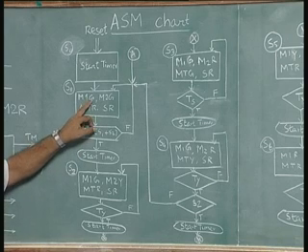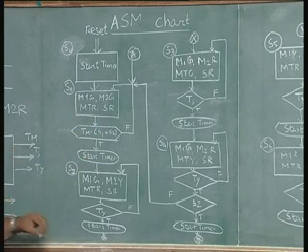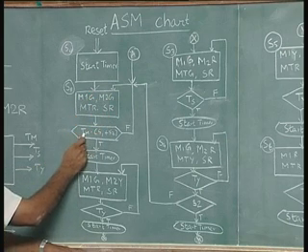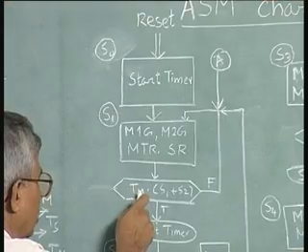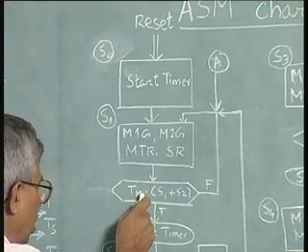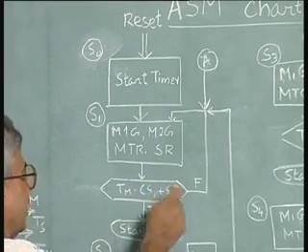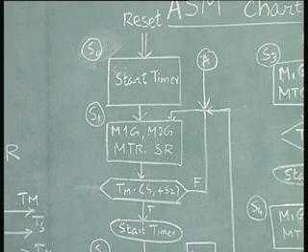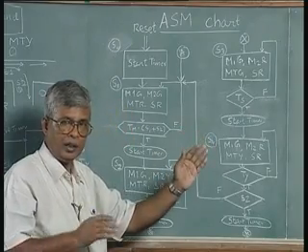So, it will be first green. Each of these states corresponds to one of those diagrams we discussed earlier. The only thing is, the machine will stay in this state until the main road duration is over. As long as the main duration is not over, or if one of the sensor signals S1 and S2 is not on, in either of these two cases you continue to be in the main road flow, green from left to right, green from right to left.